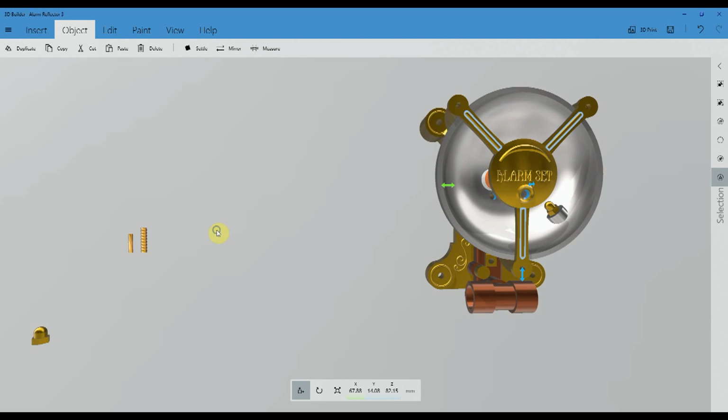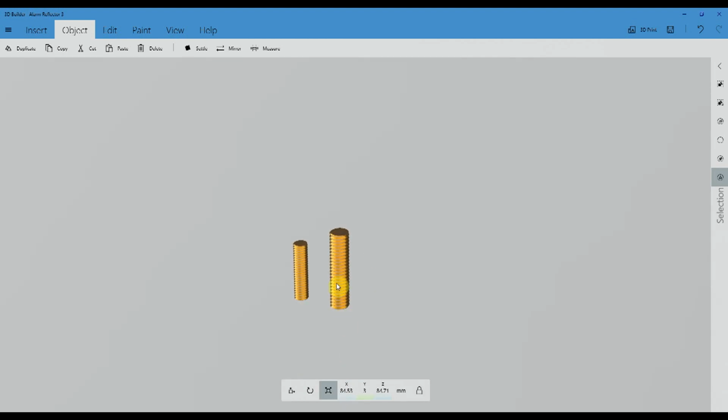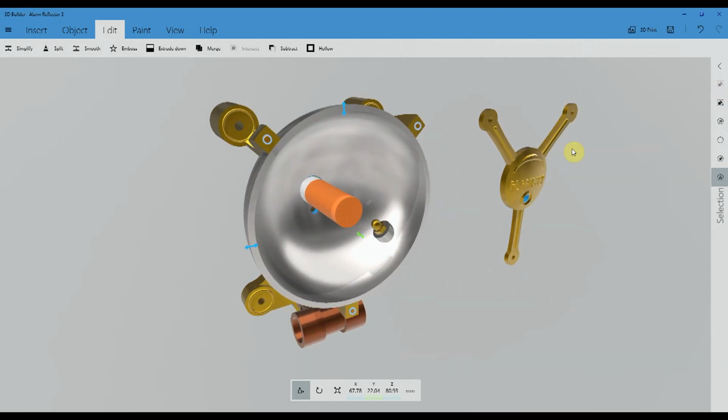I also added those 3 rod shapes, oval shapes. Now I'm going to add the M4 and M3 screw threads, which is unbelievable in my petty small mind. The fact that you can actually subtract a thread and get it so good that, once it's printed, you can just use a normal machine screw and screw it in. I've used that on the motorized Kraken gauges. So I've rotated them and lined them up with the 3 M3 holes that I want, and just going to move them in and out to make sure they don't burrow right the way through, and then subtract them. It's that simple and incredible.